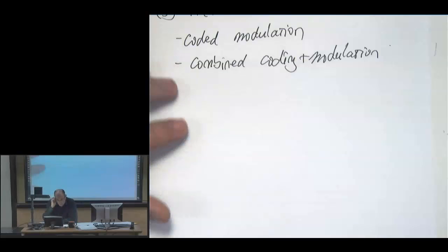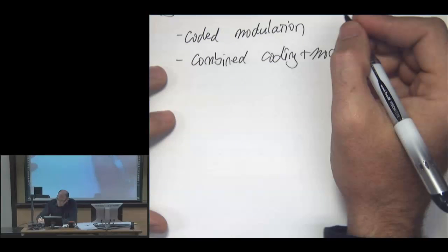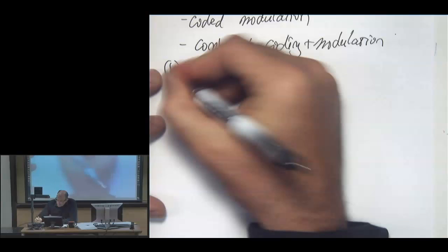It's kind of cool, and it uses a similar type of Viterbi decoder, but it hasn't seen wide use in wireless. One of the reasons is that you're typically then tied to a modulation. And what we'll see later in the class is that when you use a convolutional code, you can change the modulation. And we like to change the modulation based on what's happening in the propagation environment. All right, so that's trellis coding. I put Viterbi decoder here.